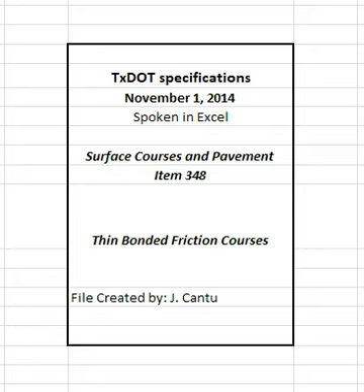4.5.2 Mixing and discharge of materials. Notify the engineer of the target discharge temperature and produce the mixture within 25 degrees Fahrenheit of the target. Monitor the temperature of the material in the truck before shipping to ensure that it does not exceed 350 degrees Fahrenheit, or 275 degrees Fahrenheit for WMA, and is not lower than 215 degrees Fahrenheit.